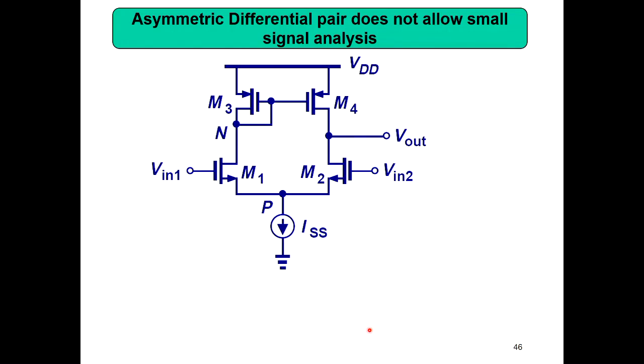So whether it is perfectly symmetric or not. It is not. Why? Because these two transistors may be identical, but here you see this point is connected here, it's kind of diode connected. But here, this is different. When you look from here up, you see R of 4. But when you look from here, you don't see R of 4. So this is not symmetric. So how will you find out the differential gain then?